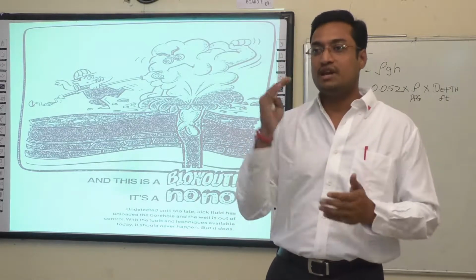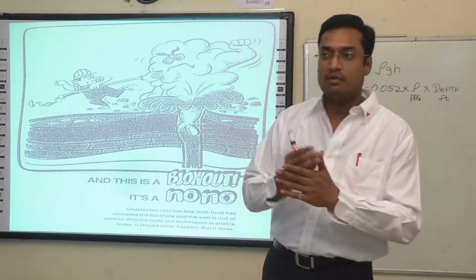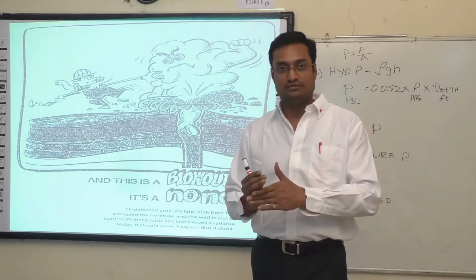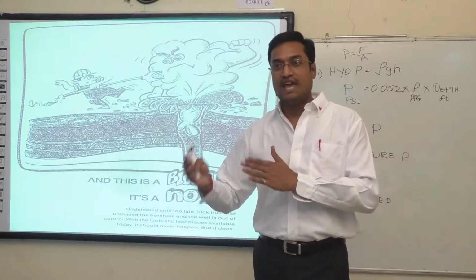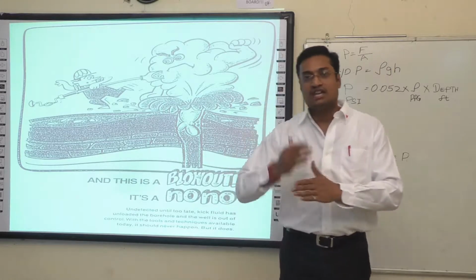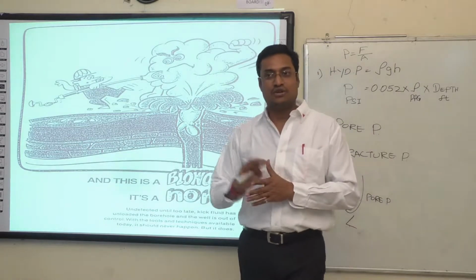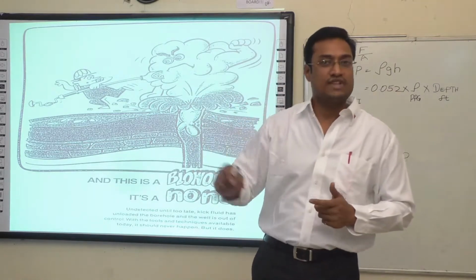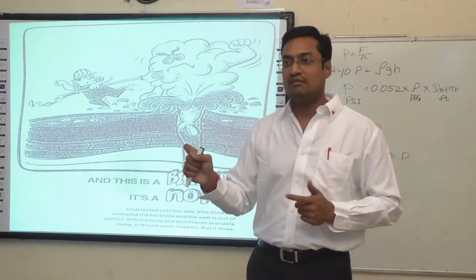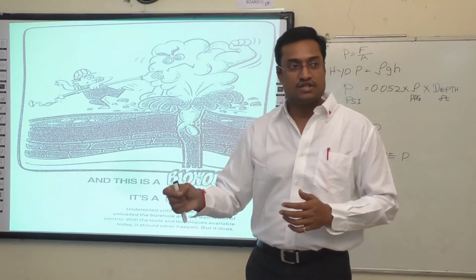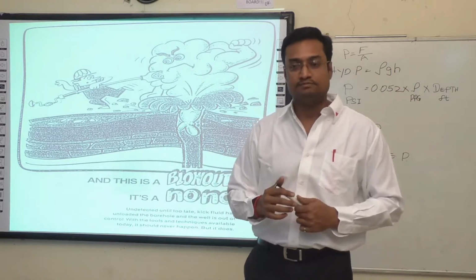It has to be confirmed whether it is a real alarm or a false alarm. If it is a false alarm, it is well and good. You proceed with drilling. Every time you get an alarm, you stop drilling and confirm. It is not that you say, no, that is a faulty switch. If it is a faulty switch, stop drilling, replace the switch, and then proceed with drilling.